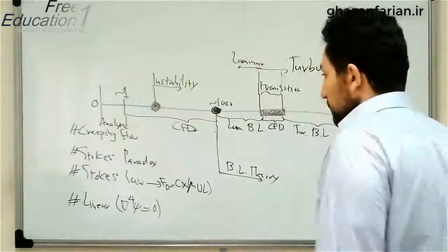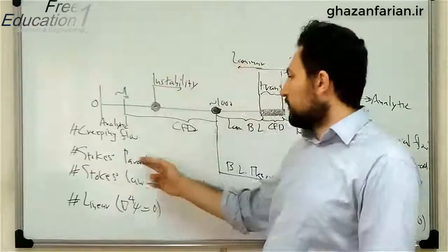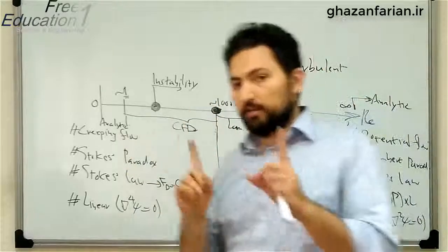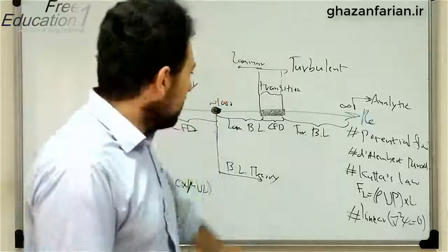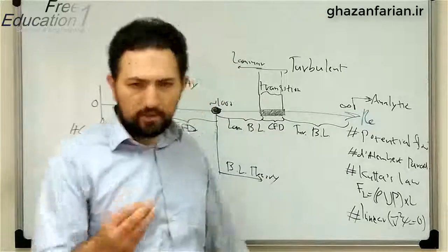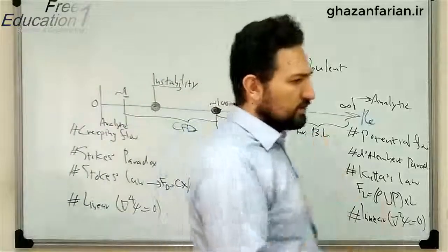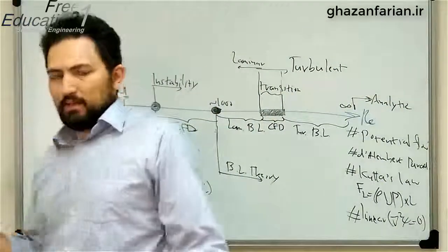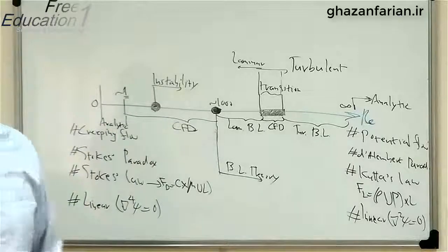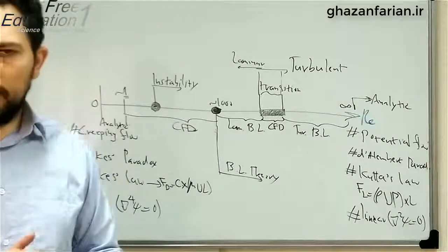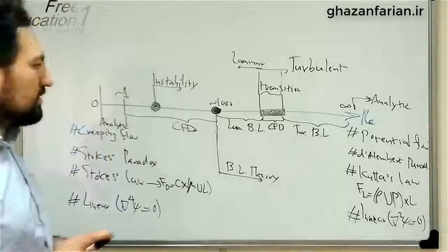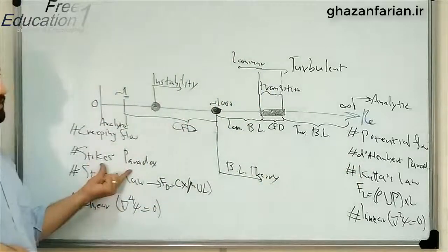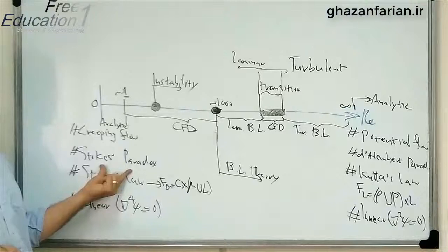So it can be concluded that the two-dimensional Stokes flow is impossible for external creeping flow. And the D'Alembert paradox here says that the drag force exerted on any arbitrary object placed in a potential flow is 0. Apparently, this is a paradox because we all know that the drag force exerted on different objects is not 0. So this is the D'Alembert paradox, which talks about the drag force. Here we are talking about the possibility of two-dimensional Stokes flows.